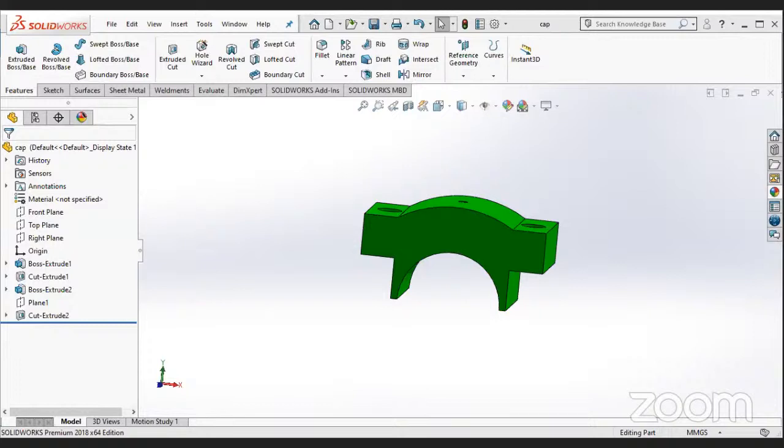Okay, here again you can make it half, and you can also mirror it on the other side. There are many approaches through which you can start drawing this. It depends on the dimensions given accordingly. Let's start making it from one side. Let's make the first bigger circle of 76 diameter and extrude it to 10.